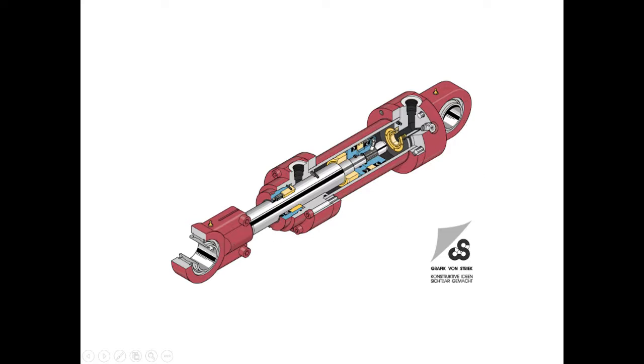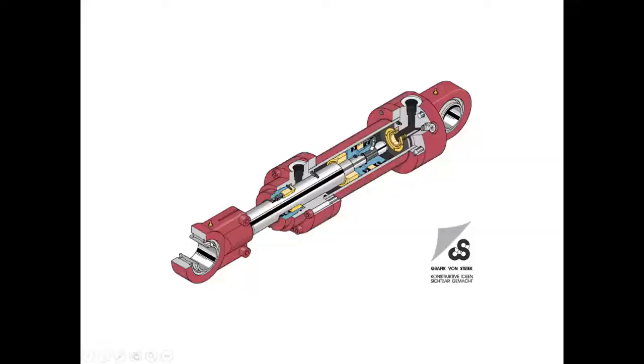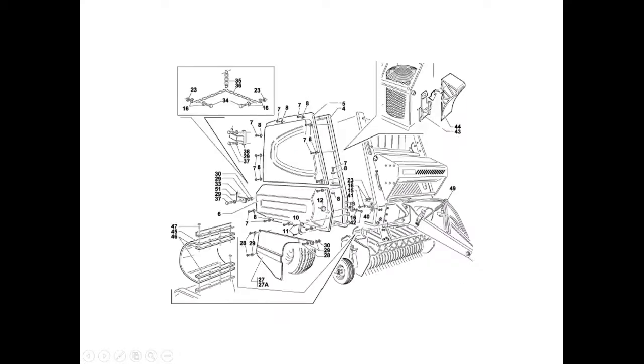The spherical part of it, even if there is a slight misalignment, will rotate like this and ensure a small rotation. It is not like a full drive rod, but the small rotation helps it align itself. And then even if you fix the inside thing very rigidly, it will sit properly. This inside part is nicely fixed to the thing here, and then there is a lubrication also. There is a small lubricating device here, a lubricating nipple, which ensures that it gets lubricated.